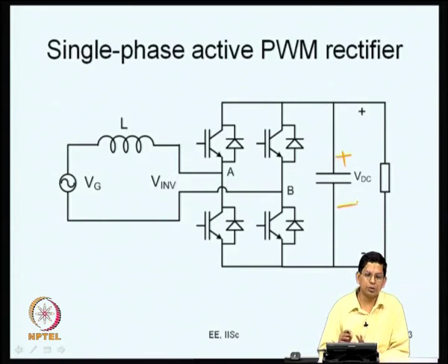The outer voltage loop makes the DC bus voltage steady, and the inner current loop is much faster. So, you can presume that the voltage is steady, and what the inner loop does is control the current, and it basically specifies the amount of V inverter that really requires to be applied now. So, if you say that DC is fixed, then you can modulate the inverter appropriately, that is, you can switch the devices appropriately, so that you get the V inverter that is desired.